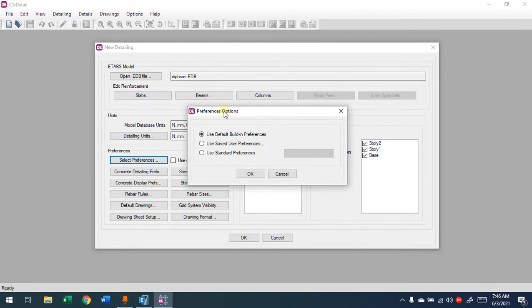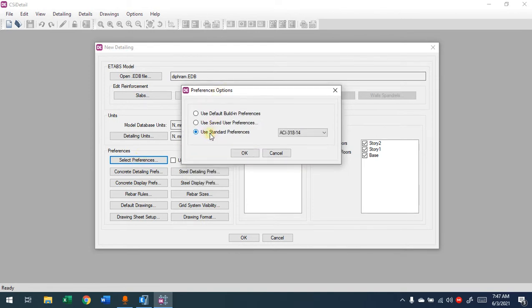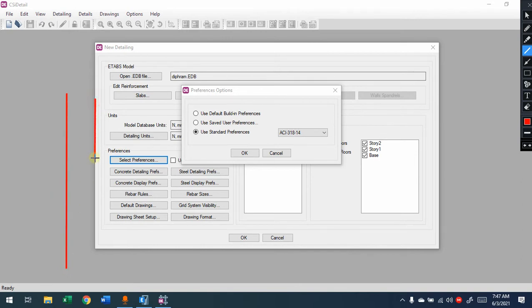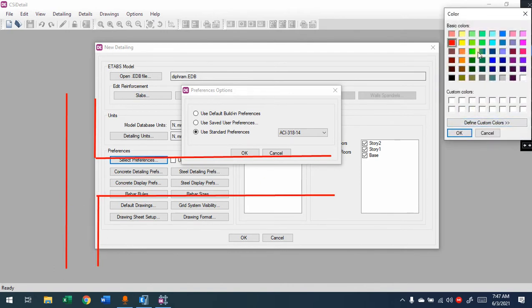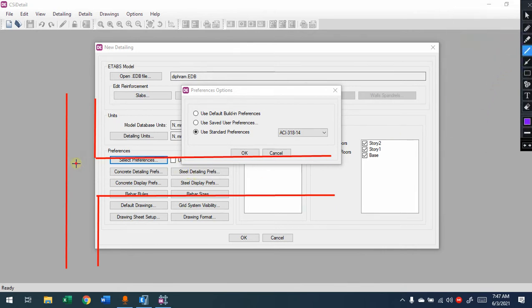Are you going to change the code, especially with the zone things? Remember, you might design this one with something else, but the detailing can be according to something else. What do I mean by that? In case you have some columns, let's say there's a column here, and there is a beam, then the reinforcement that we're providing, let's say at the top, there is a distance that goes from here. How much is this distance? According to the code it is changed. Maybe it comes like this and there is bending.